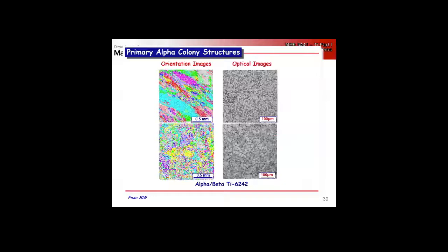It's the inverse pole figure coloring. So it tells you basically which crystallographic pole is going to be parallel with the sample direction. In this case, we're looking at the sample direction that's orthogonal to the sheet. It's not a single grain. We see that it's not a single grain because this is the same magnification. These are the exact same samples, the same magnification. So we see this is hundreds and hundreds of grains that are all colored the same way.